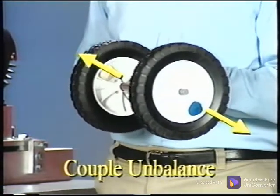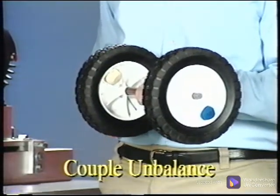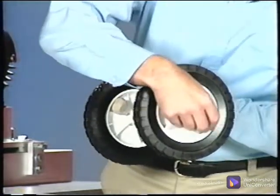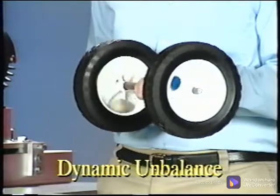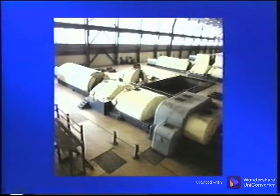The phase data will indicate the ends are moving in opposite directions. Couple unbalance must be corrected with equal amounts of correction in 2 planes, but 180 degrees opposite each other. Any combination of static and couple unbalance is called dynamic unbalance. The phase data from end to end could be any combination and will usually require correction weights in more than one plane. Manufacturers sometimes provide specific locations for adding correction weights, and these must be used.